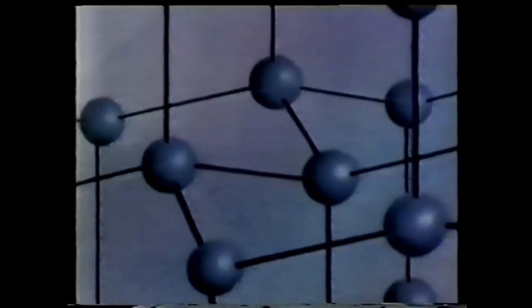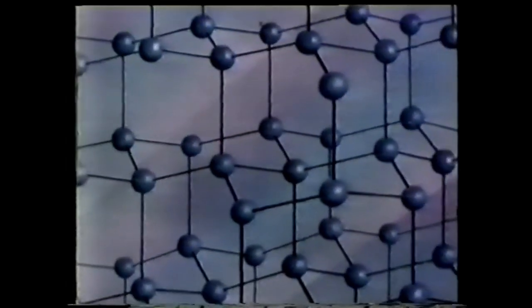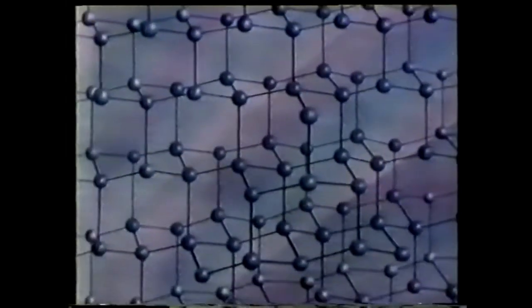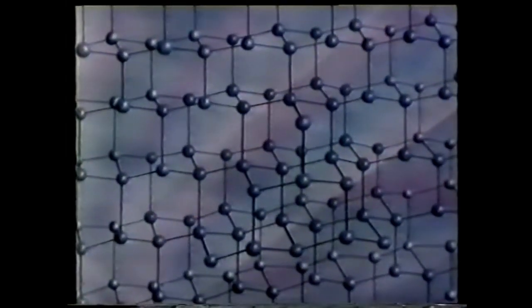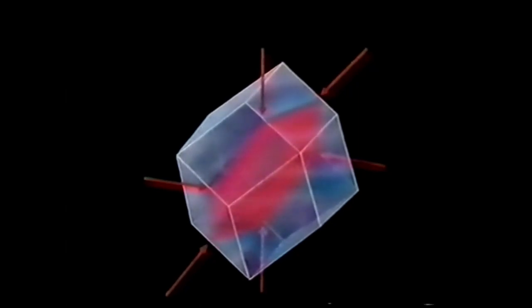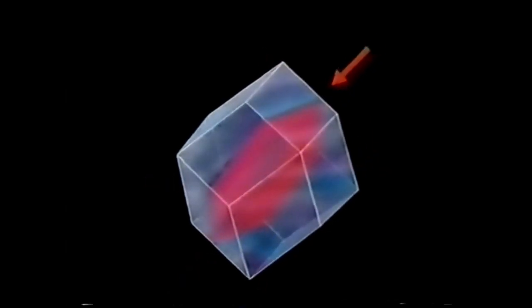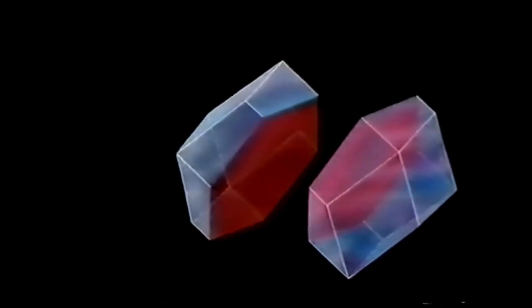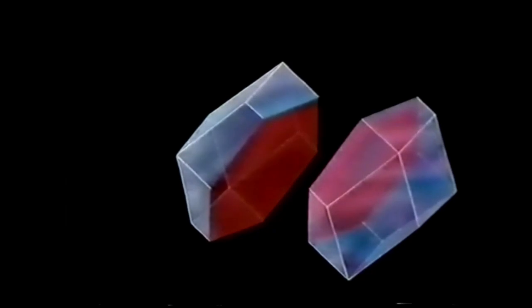Although hard, diamonds are also extremely brittle, and they can easily chip or fracture. The structure of the crystal is made up of millions of regularly spaced carbon atoms. Due to this regular shape, the stone has its strong points, but also its fracture planes. These weaknesses are used by jewelers when they come to cut the stones. It's shock to these weak fracture planes which causes the industrial diamonds to chip. This can pose problems in industry. What's needed is a diamond that doesn't chip.